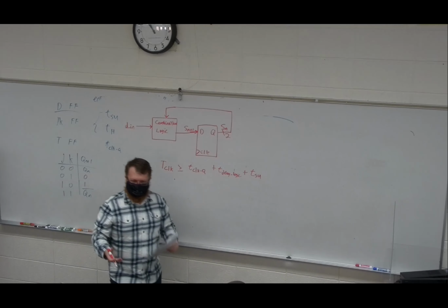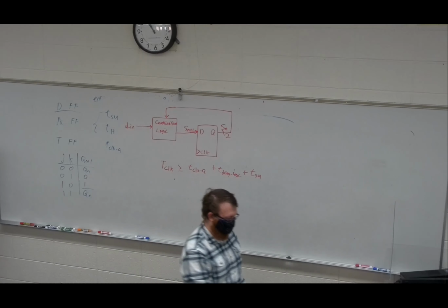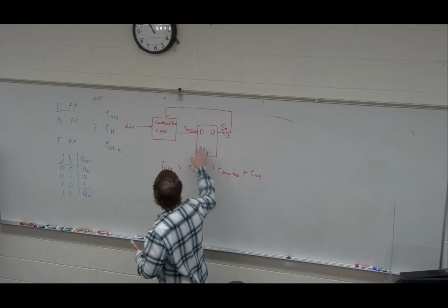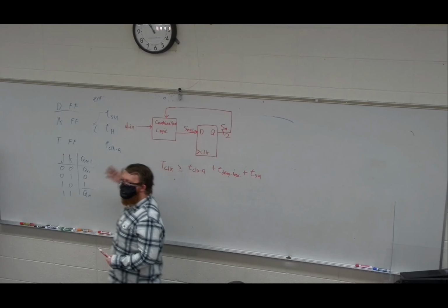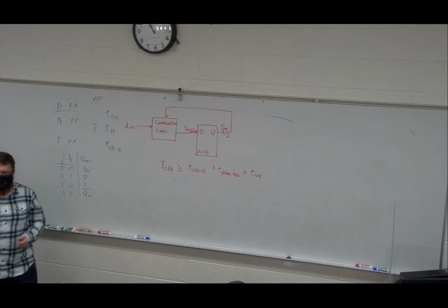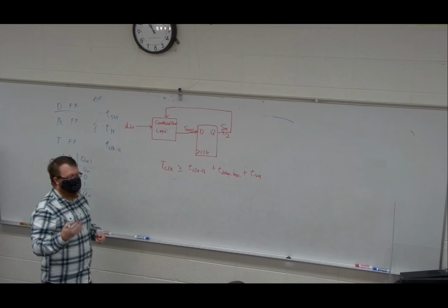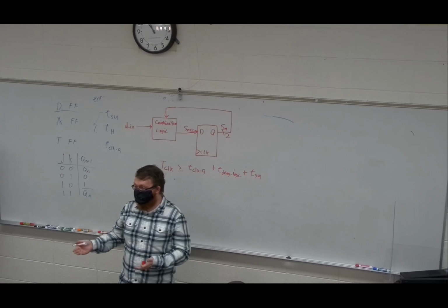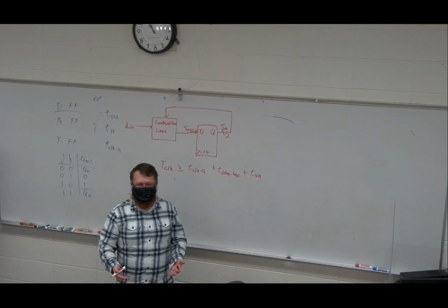We're going to take a pause on the sequential logic, and move on to some of the ideas that we can build up other than state machines using D flip-flops. One of the most important, and I mentioned this last time, is called the register. The register is just a series of D flip-flops that are used as memory, right?